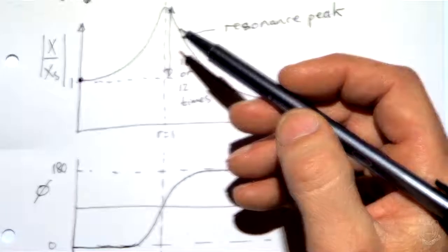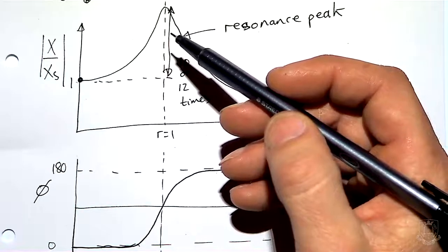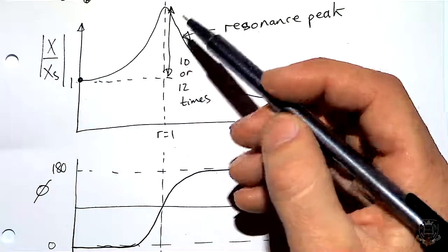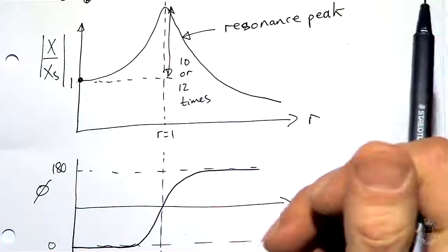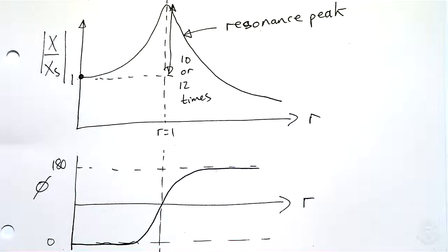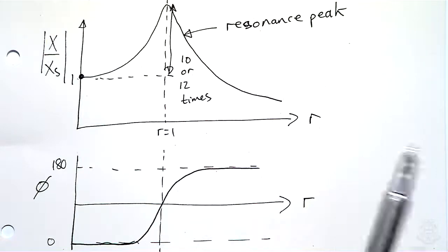If your system, like an aircraft, and many other systems have the same kind of thing, spends all of its operational life in a dynamic environment, then it's continually subjected to vibrations, isn't it? So this is one reason why you need to be concerned about it. The transition in phase, again, we can observe this physically: for low frequencies we get this kind of phase effect between the forcing signal and the response signal, and then we get this transition at resonance going to 180. So this matches our physical observations very closely.